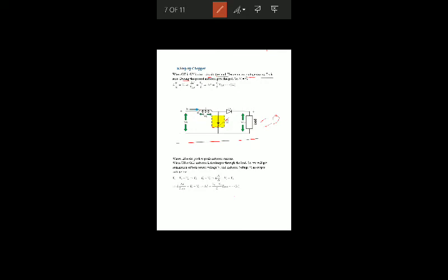The whole voltage drops across the inductor, so VL is equal to Vs, where delta I is the peak to peak inductor current. We can now represent this mathematically: V naught is equal to 0 and VL is equal to Vs. These are the two conditions that occur when the switch is closed.